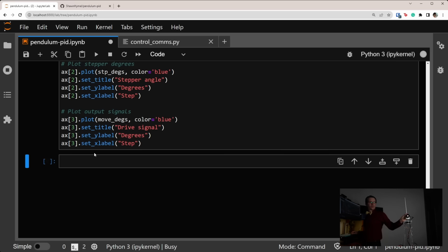That keeps it for a while. Not much on the oscillations, and it's just struggling to keep up. This is what we want. We want the integral term to make up this difference. This is that steady state offset between where the set point is and where it's trying to get to, or as best as it can get. So we're going to keep it at 0.3 and see if we can get Ki, our integral term, to make up that difference. I'm going to guess at 0.1. It usually starts much lower than Kp, so let's try that and see what happens.